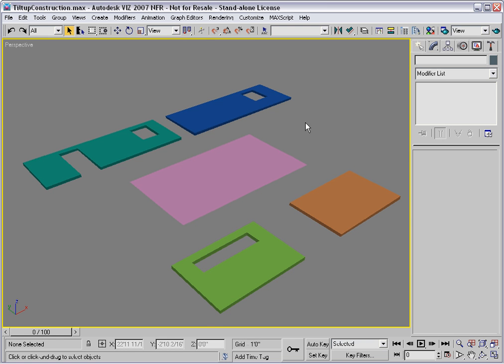I've opened the tilt-up construction sample file to explore a modeling technique that relies heavily on alignment. It will bring together much of what you've learned in this section. With tilt-up construction, you create sketches of elevations in the top viewport and extrude them to create separate 3D objects of your walls. Then you tilt them up and align them into position to create a 3D model of a building. My thanks go to Ted Boardman for pioneering this powerful technique.